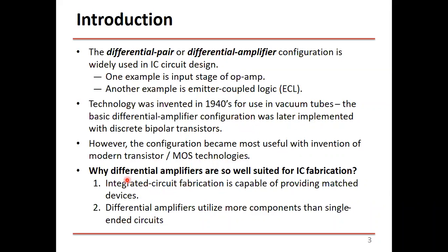We ask the question, why are differential amplifiers so well suited in IC fabrication, as I mentioned, rather than discrete components? Well, the first reason is that integrated circuit fabrication is capable of providing matched devices. If you have two transistors and they are required to be identical, you cannot do this unless you have an integrated circuit, because you fabricate both transistors at the same time in the same process. Also,